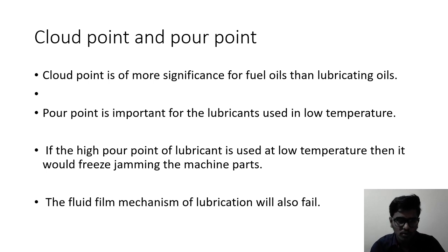Cloud point and pour point. Cloud point is more significant for fuel oils than lubricating oils. Pour point is important for the lubricants used in low temperature. If a lubricant with a high pour point is used at low temperature, then it would freeze, jamming the machine parts. The fluid film mechanism of lubrication will also fail. So this is about the cloud point and pour point.